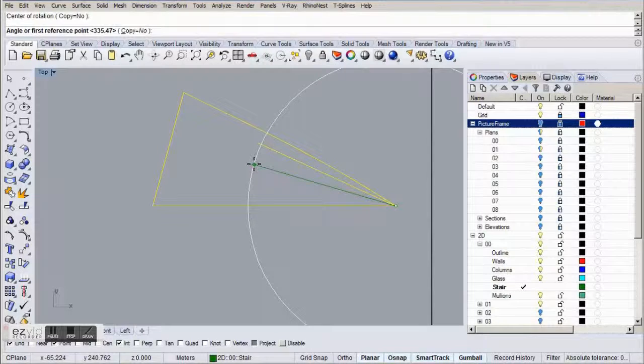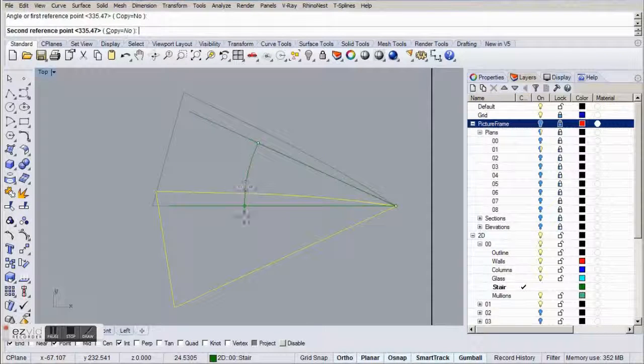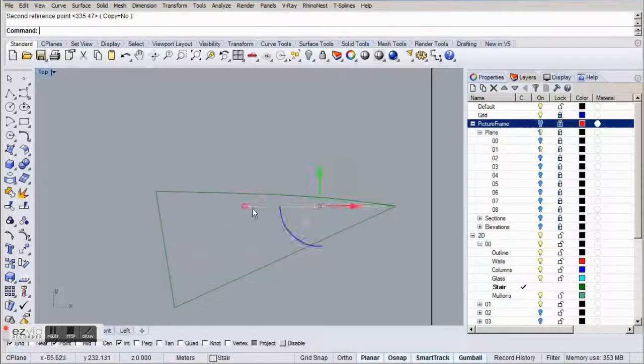Now we're going to use our line we previously drew, so we know exactly the position it had before. If you hold Shift, it will snap to certain angles. Or you can use Ortho, which also does the same thing. So let's delete our line. We won't be needing it right now.